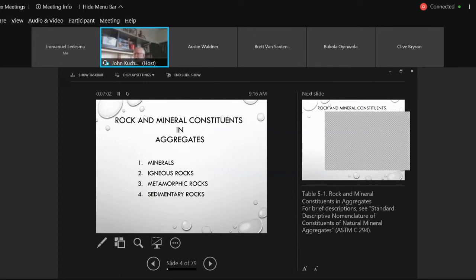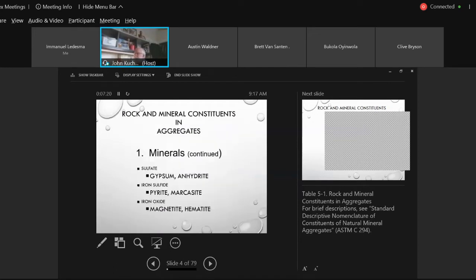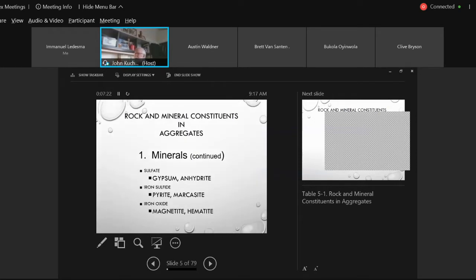City of Winnipeg, I believe, will not allow 100% crushed, whereas MI will allow 100% crushed for concrete. They're both acceptable. They're both doable. They just all have different physical properties. It's going to affect the performance of the mix, more from a workability criteria because of the rough texture. Again, different minerals. I'm going to go through this.